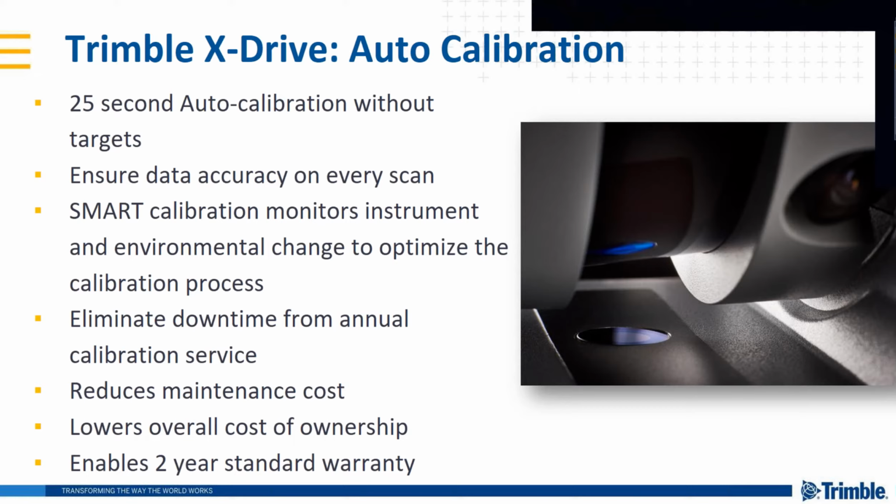As long as the scanner is mechanically sound, and one of the things that will fail such a calibration is, of course, if that isn't the case, you will basically not have to send the scanner back to us for that calibration routine, as it does it before each individual scan. The time it takes varies a little bit on how much you scan, whether it's temperature stable, whether light is stable, these types of things. It monitors that. And whether we have to do it on each individual scan going forward, is something we are currently looking at in order to maybe get the time even further down.